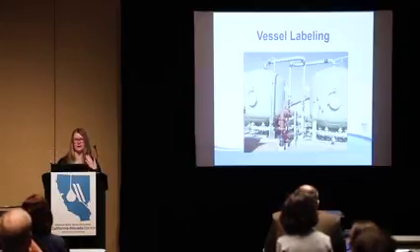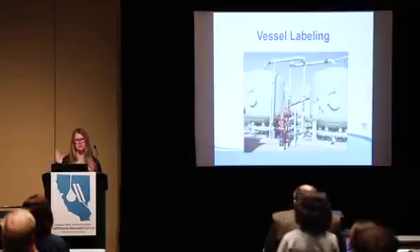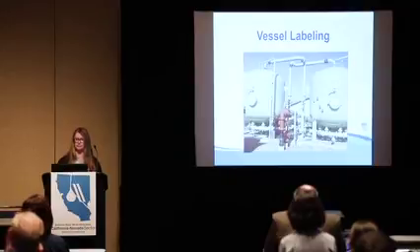In the event that the configuration gets switched, because if we do a change out on one vessel, then once that vessel has the new GAC material in it, we're going to switch the configuration, and then the lead becomes the lag. And so that was important for us to keep track of.